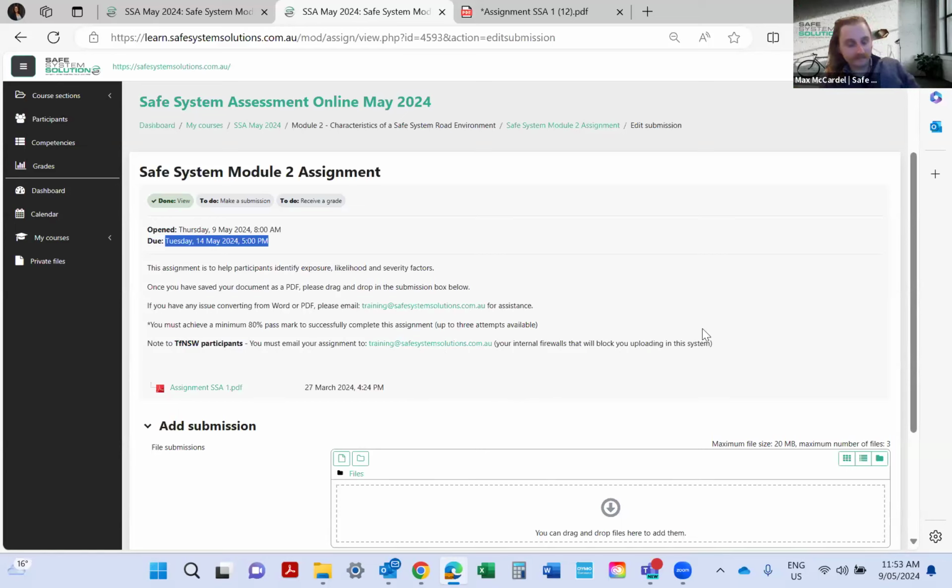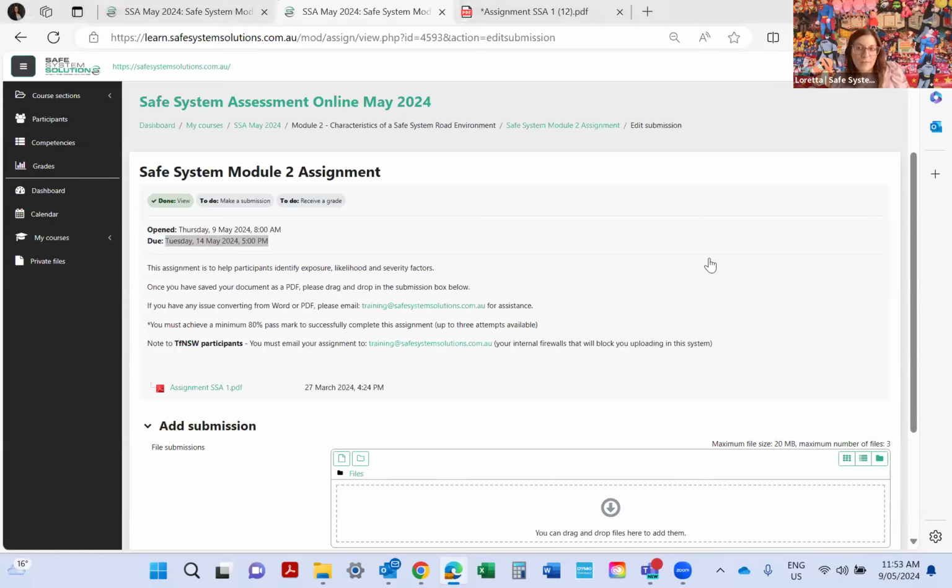And yeah, question time. So the question earlier was, is the reduction in risk caused by the reduction of the number of conflict points offset by the increased number of vehicles going through each conflict point? I'm guessing that's to do with the roundabout or the compact roundabout. And yes, the reduction is to do with the conflict points, but also the impact speed and the impact angle. So it's multifaceted. There's many reasons why roundabouts are more favorable compared to traffic signals.